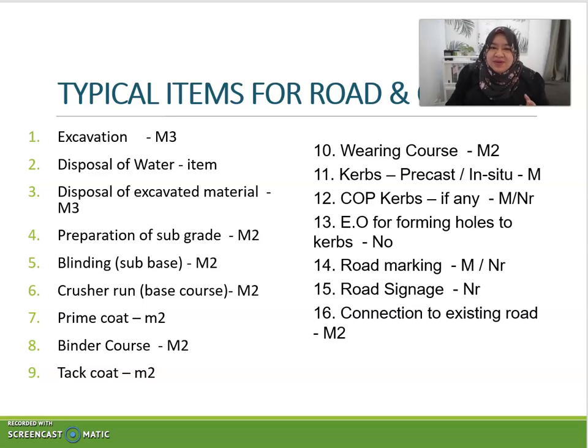Of course, you need to refer to the relevant section. If it's excavation, it will definitely be section D of your SMM. So first, we have the item for excavation to reduce level. And then, of course, if you are referring to section D, you need to have items together with the excavation item like extra over in rocks, disposal of water, disposal of excavated material, filling if you have any.